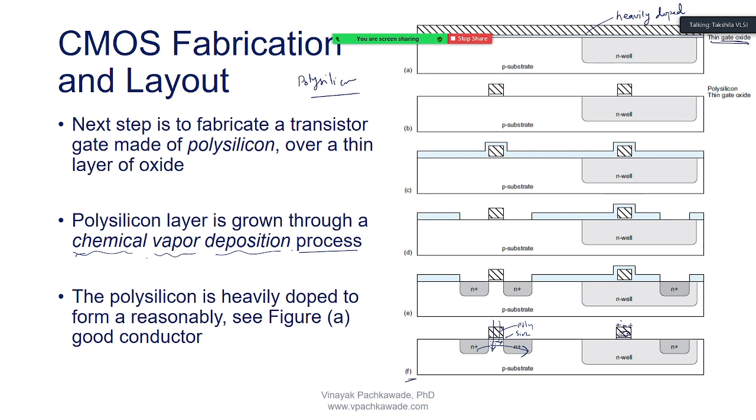It is an insulator, but it may not be a perfect insulator. So obviously there will be some leakage, in which the charge carriers will try to cross the oxide, and that's called the tunneling effect, and that is a possibility. But normally this is not the case. And here the gate is completely made up of polysilicon, no, sir? Yeah. Okay, sir. Thank you.